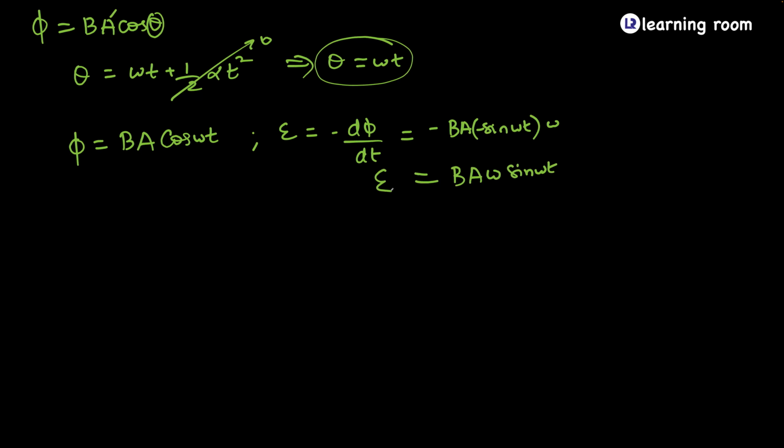But in reality, coil will not have one turn. You look at this itself. This itself does not have one turn. You can do nothing with one turn. So it will definitely have N number of turns. So when N number of turns are there, you just need to multiply with N here. And this gives us a point stating that the EMF is equal to NBA omega into sine omega t. This NBA omega is what can be replaced with E naught. You call it as E naught into sine omega t, which is going to be the EMF.